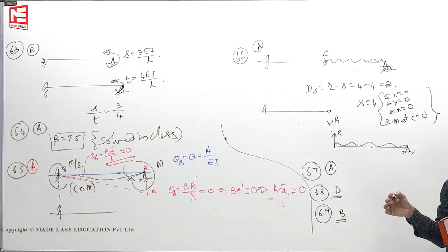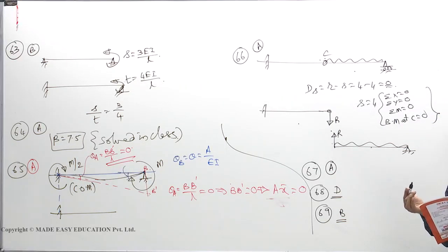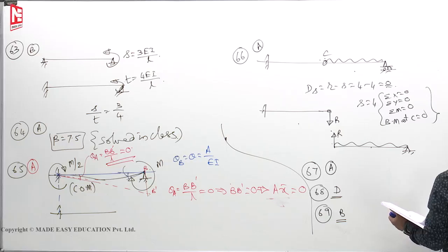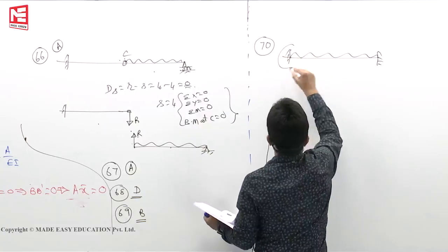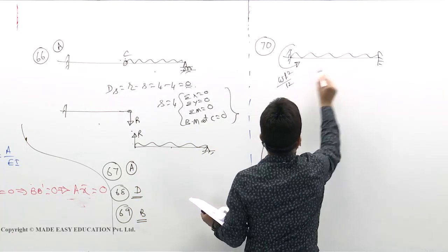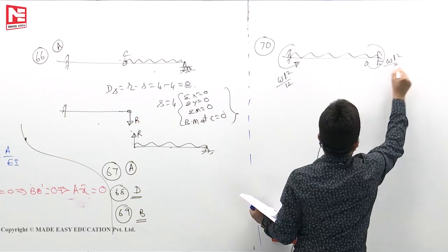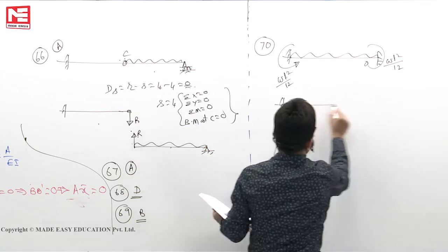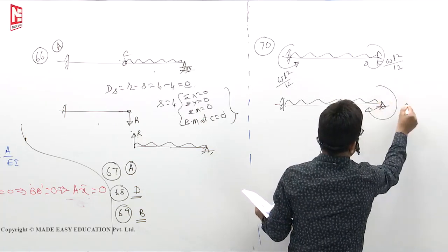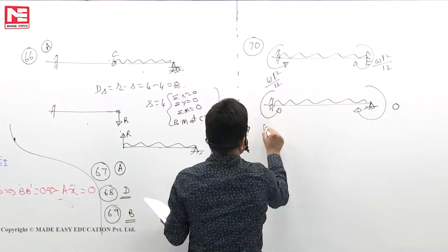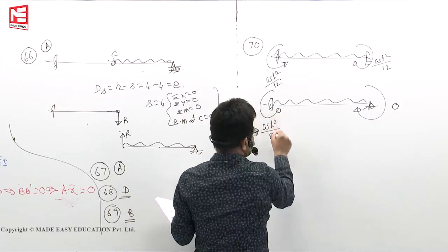Both are correct, but why are they called essentially stiffness methods? Because you are using stiffness factor and carryover moments. Next, degree of fixity at the supports is lessened. Supposing that you have a fixed beam subjected to some UDL, you get WL square by 12 at both ends. If degree of fixity is lessened, supposing that you make a hinge, because degree of fixity is now 0, fixed end moment is 0. Here, WL square by 8, which compared to this is 50% more.